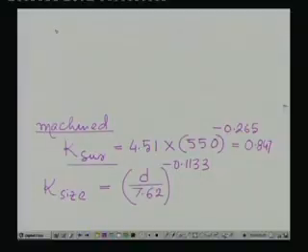Okay. What I am trying to say is that in this case we know that sigma equals M y by I, or it is given as M by Z, since I by y is Z. If we consider this equation, what can we get? This stress value we can find out.